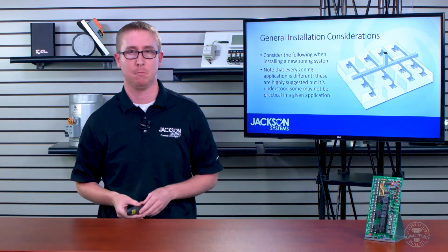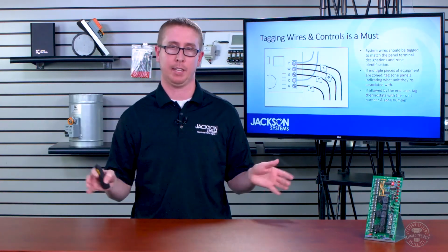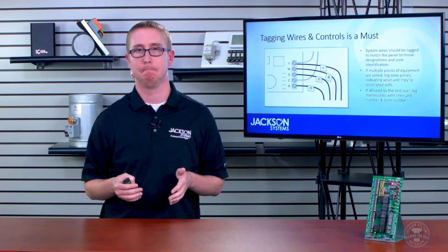General installation considerations. This is where we're just going to start talking about kind of rules of thumb, so to speak. Again, note that every application is different. These are just our suggestions, but they might not be practical on any job site or any application. So the first thing is just tag everything if you can. Tag your wires to make it impossible to miswire the thermostats or the dampers.